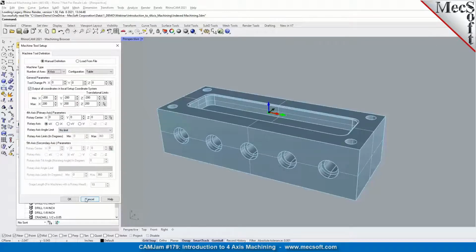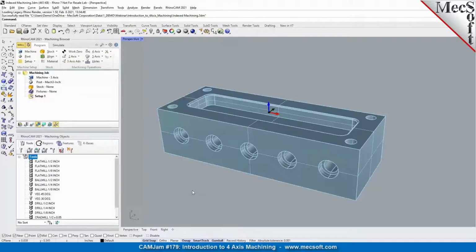So in addition to your 2 or 3 linear axes, a 4-axis also involves a rotational axis. The rotational axis could be defined as an A axis or a B axis, or whatever axis code your machine tool expects, which can be configured in the post, and the rotation will typically be output in degrees. So you will have 2 linear axes, which could be translated in inches or millimeter units, and then your rotational axis will be output in degrees when we program 4-axis or multi-axis toolpath. Typically, in most cases it would be two linear and a rotational axis when you program continuous.